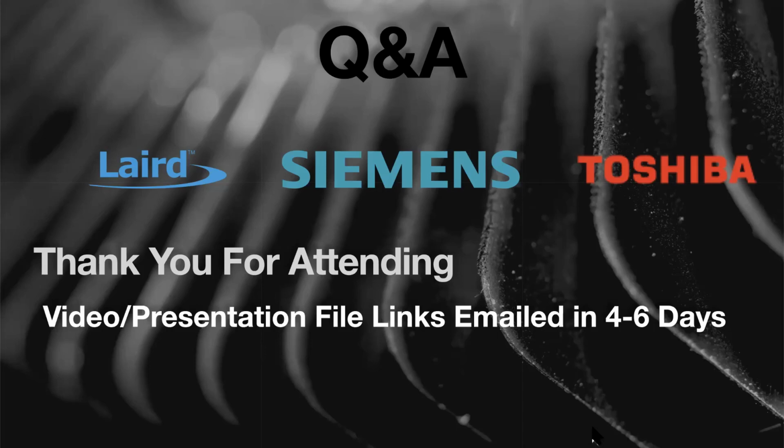We do have a system, actually a set of systems, which we call the power cycling tester, which can exactly do the same. So it can turn on and off the heating power in a cyclical way. And for each cycle, we can measure the temperature change, so the delta T and the maximum TJ. And from time to time, as you keep on doing the cycling, we can capture structure functions to make sure that nothing happened to the structure. If the structure is degraded, we can capture that. So we do have this system available, and I'm very happy to talk about this in detail to the person who asked the question.